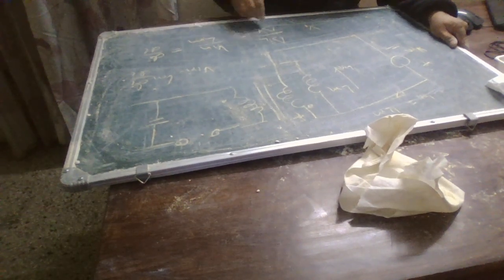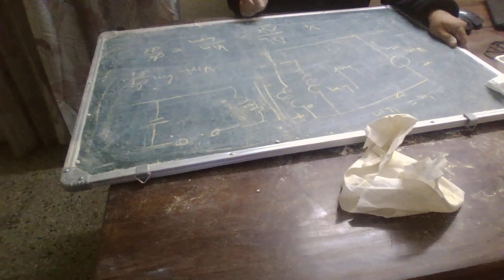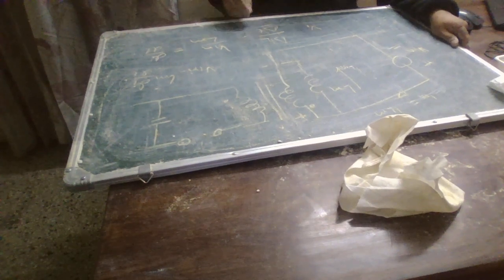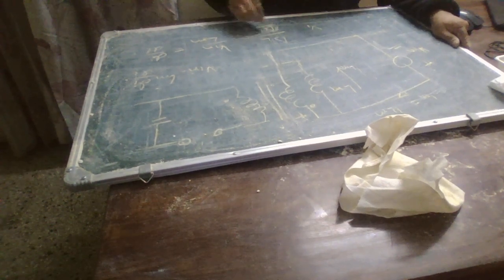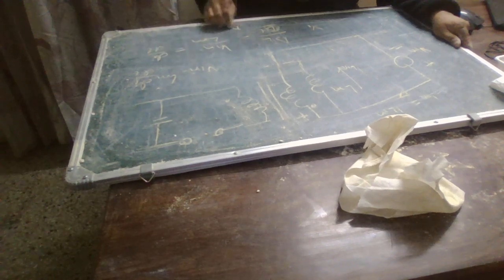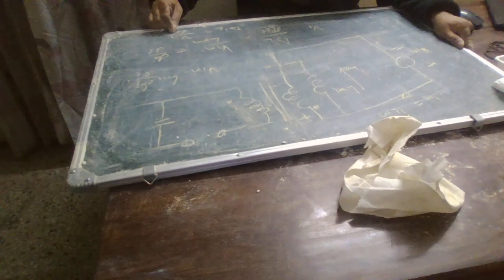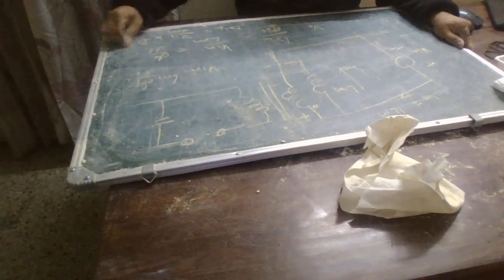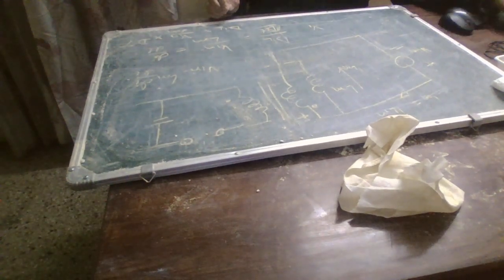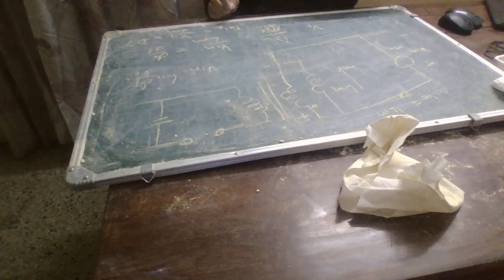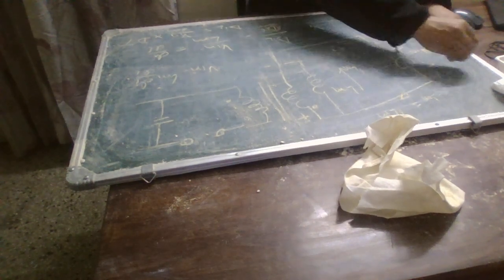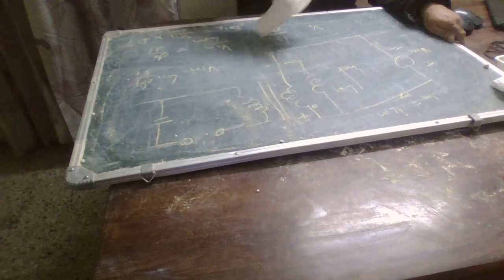Now we know delta t here was dt, so we can replace it by dt. That means delta IL is equal to V input upon LM into dt. So this is our change in current in the transformer magnetizing inductance when the switch is on or the switch is closed.